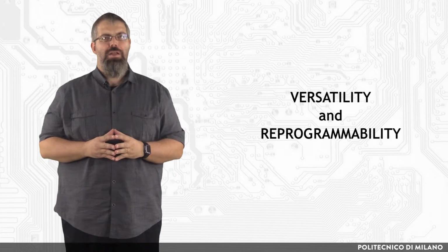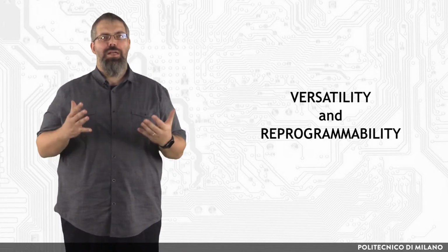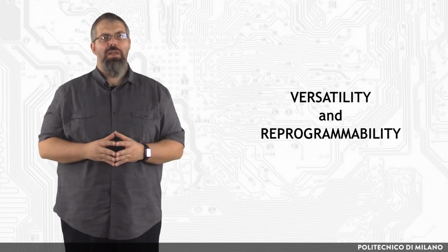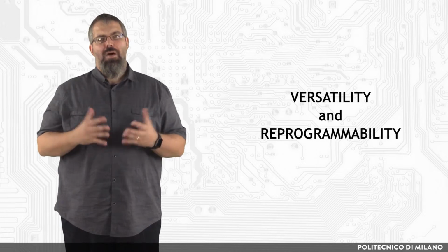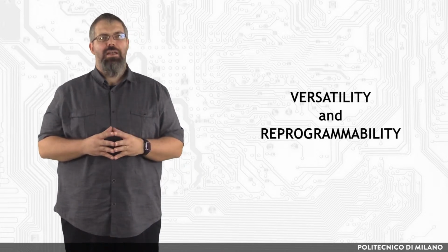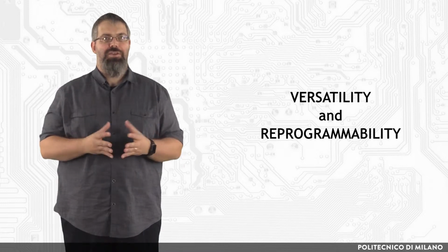Only a few years ago, the algorithms that could be implemented in a single FPGA chip were fairly small. At the beginning of the century, as an example, the largest FPGA could be programmed for a circuit of about 15,000 logic gates at most. Now, to give you an idea of how much 15,000 logic gates are, think that a fast 32-bit adder requires a couple of hundred gates. Therefore, you can easily see that the capabilities of such devices were somewhat restricted.